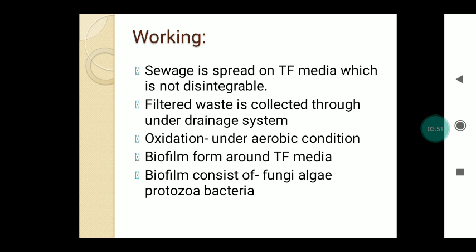This very thin film consists of fungi, algae, protozoa and bacteria, which are responsible for the oxidation or decomposition of the wastewater. They utilize oxygen in aerobic conditions, and in the absence of oxygen anaerobic digestion occurs.